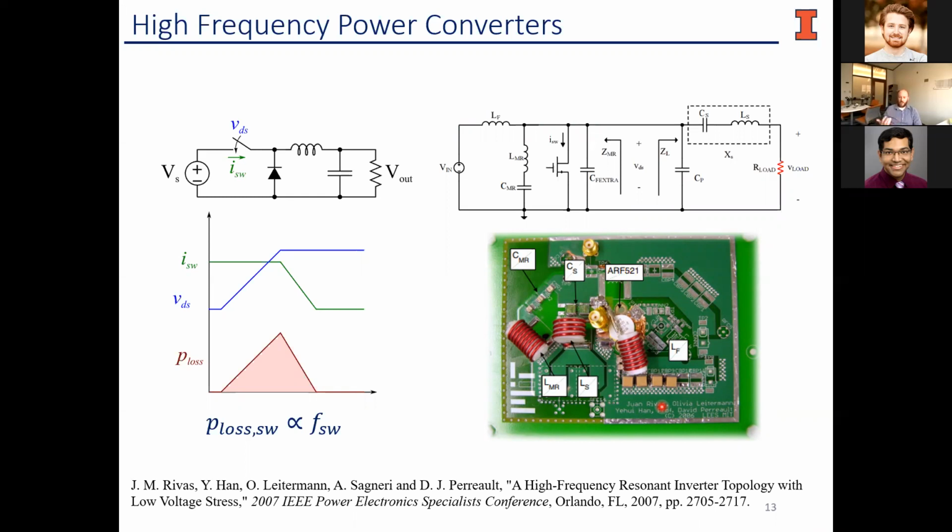And it turns out, while these converters do reach very good conversion ratios and are able to operate at very high switching frequencies, they haven't been very successful in driving down the power density. We can see here they've got these air core inductors that end up being relatively large. And not all of these components are completely lossless. There are parasitics, and those parasitics don't operate well at very high frequencies. So overall, just going to higher switching frequency doesn't turn out to be a very good solution. Instead, we have to look at better topologies and how we better utilize the components we have.